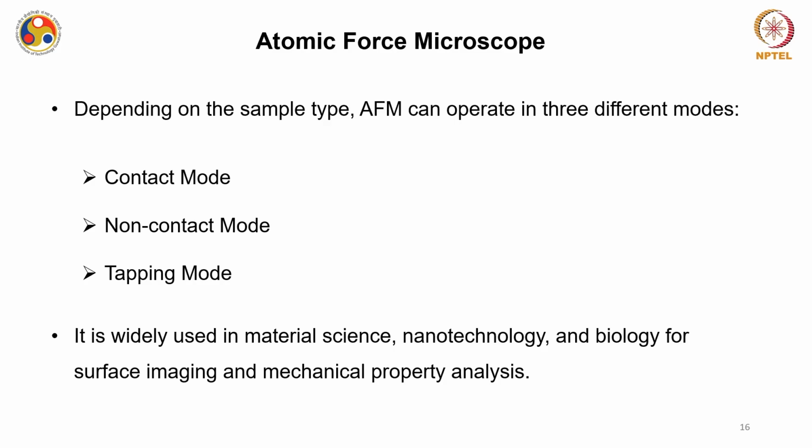Non-contact mode is where the tip is very close to the sample surface, but it is not touching the sample. And then third is the tapping mode, which means that the tip is coming very close or even sometimes touching the surface and going back. So it is basically tapping the tip on the surface of a sample.